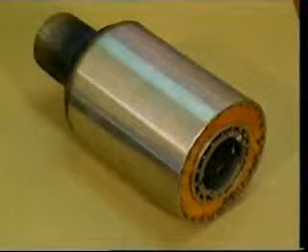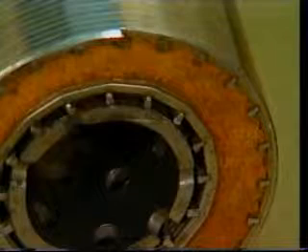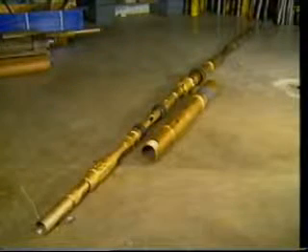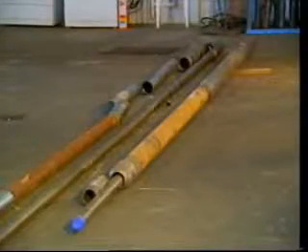Pre-packed screens and filters consist of screens pre-packed with a filter material and porous metal filters. Gravel packing techniques consist of external or open-hole gravel packs and internal or cased-hole gravel packs. These mechanical methods will be discussed in detail in Unit 2. For now, let's state that each method has an application for which it is best suited from both an economic